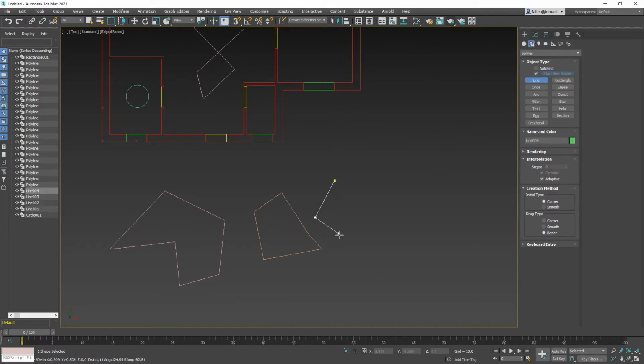If the polyline is closed, and I'm doing it really so that you see the difference, if the polyline is self-intersecting. So I just said closed, yes. So it is also a closed polyline, but it won't work for the purposes that we are doing, because it is self-intersecting. And the difference between a self-intersecting polyline and a closed non-intersecting polyline is that you cannot define where is inside and where is outside. When it's a closed polyline, of course, there's inside here and there's outside there.